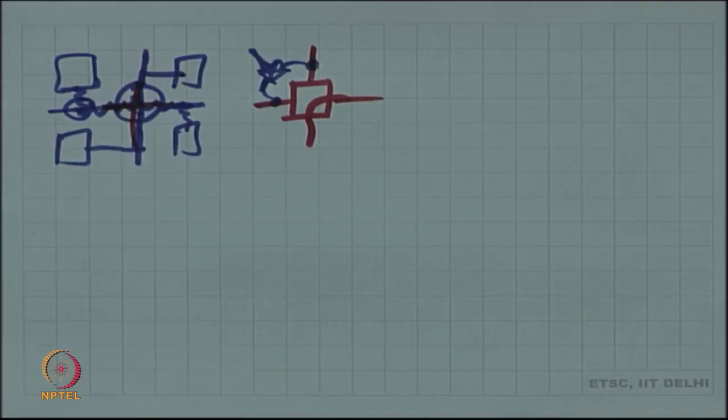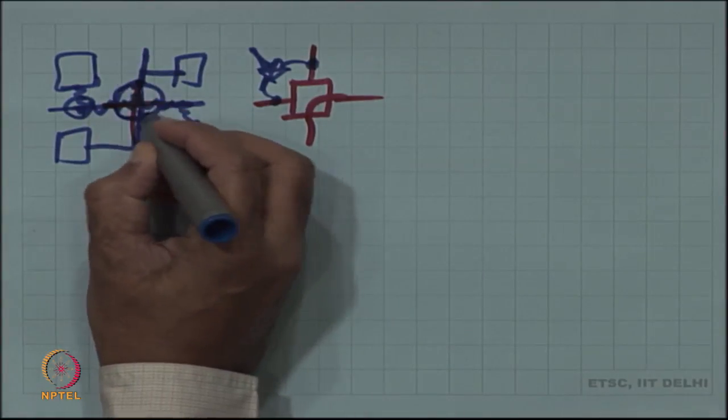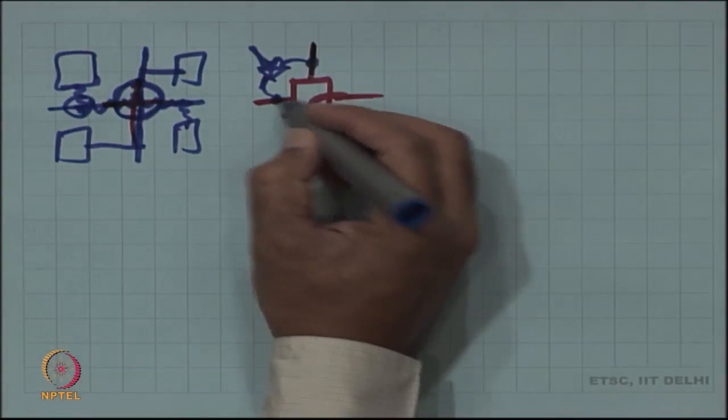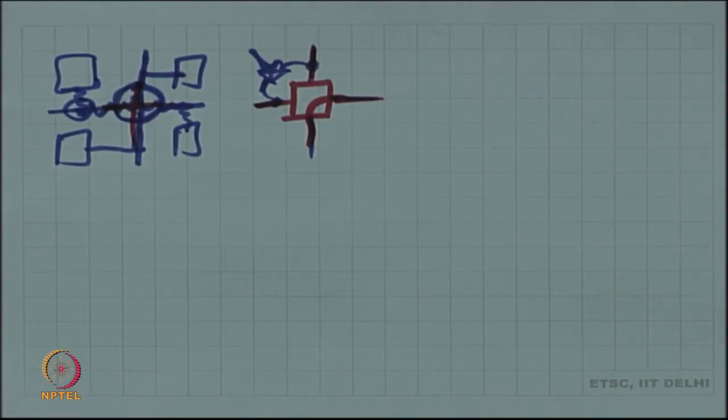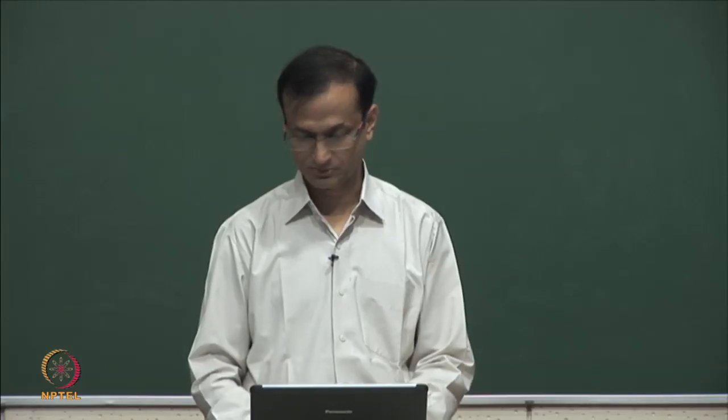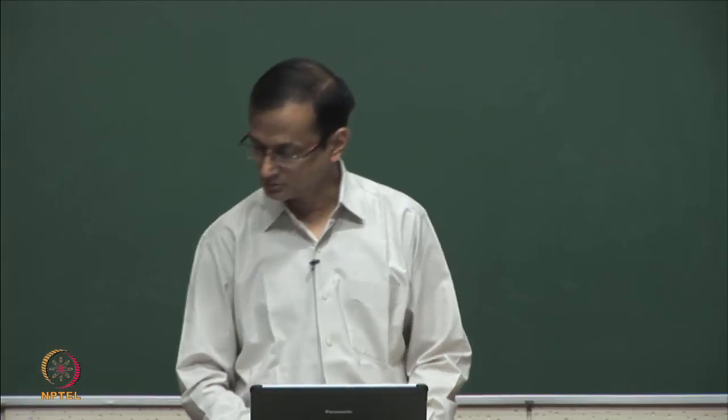So, there is one programmable interconnect there that I need to program, which is to decide whether that block is connected to that line or not. So, that is where that programmable interconnect is useful. But the more interesting interconnect is here, where I have these 4 things coming in and I decide which one is connected to which. So, all the pairs between which I would like to establish connections could possibly use that elementary programmable interconnect structure. So, how many such pairs are there?